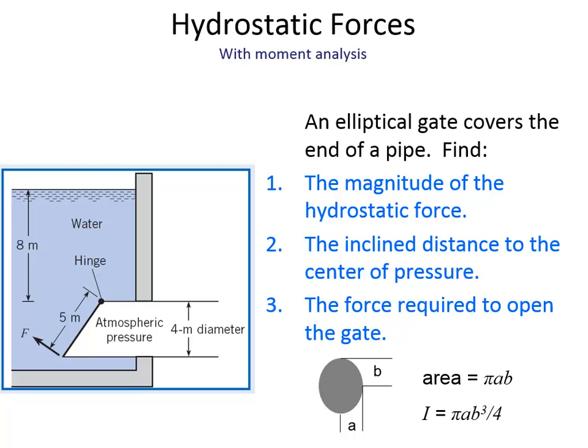Now, if you go at an angle, you're going to see that it takes you out of the tank. And so we'd extend that line inclined up to where the water surface would be. So pretend that the water surface continues. That's the y bar distance that we're going to find.